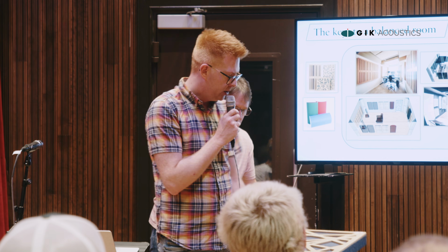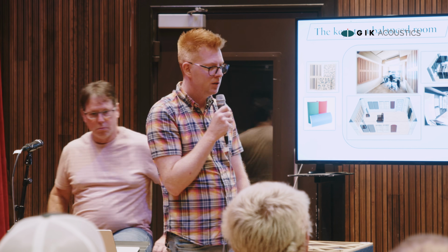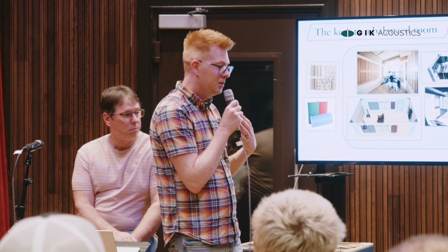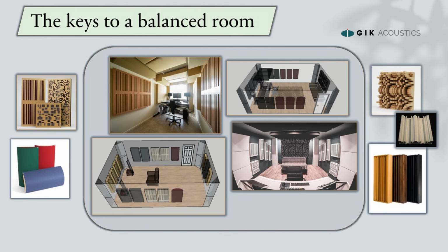You know, the best places for these types of panels, in my opinion, I mean, there's many ways to do this, but particularly in small rooms, you want to mainly have those towards the back of the room, so that you still have your reflection-free zone around the mixing area. So the sound hitting the sidewalls forwards of your ears is still absorbed, but then if you turn around and you start speaking, you're now interacting more with these kinds of panels that are going to reflect back some of your movements and your voice when you're speaking.